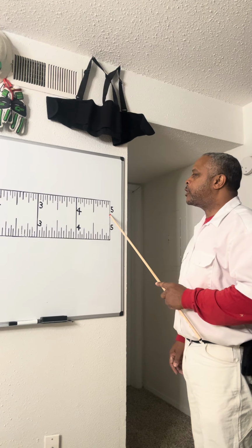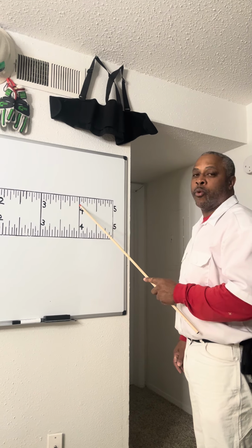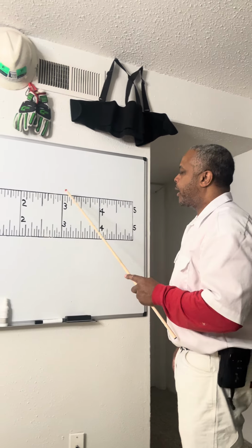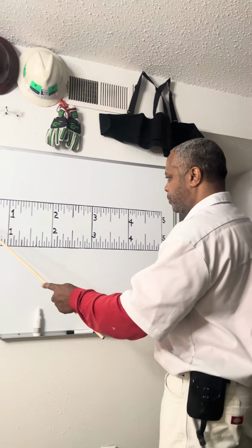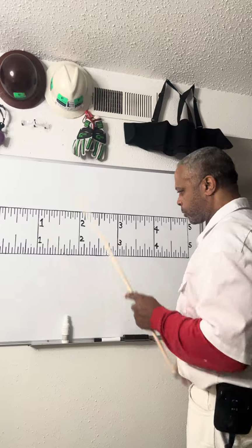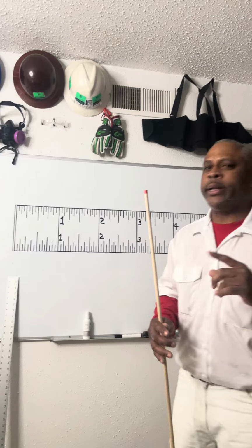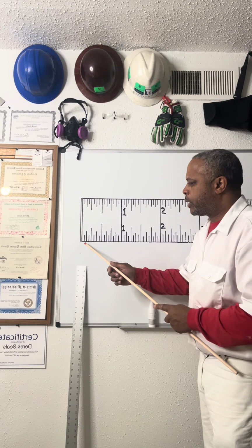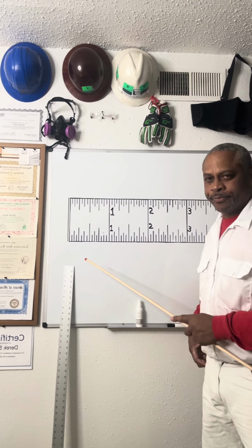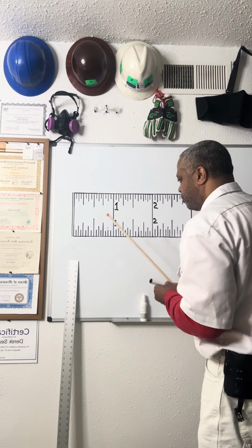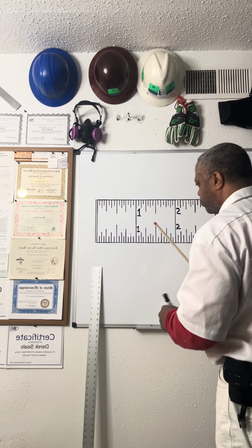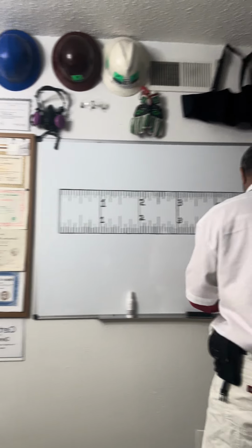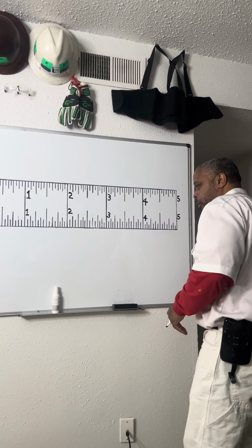At the end here is the 5th inch, between this point here and this point here. So everything going backwards this way is telling you that from here to here is 1 inch. To break this down, 1 inch: every one of these markers here is 1/16.